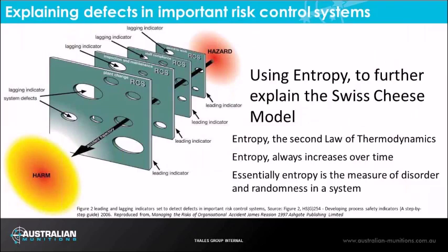The Swiss cheese model of accident causation is a model used in risk analysis and risk management. This well-known model, first proposed by James Reason, details barriers which are layered to provide defence in depth. As holes appear in safety barriers, like the holes in Swiss cheese, they eventually line up and allow a hazard to be realised. This is illustrated in the diagram borrowed from the HSE UK Guide for Developing Process Safety Indicators.